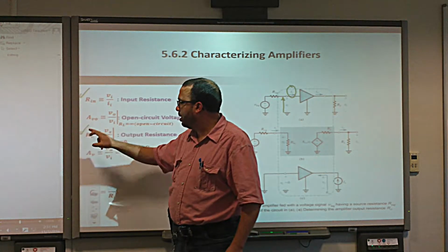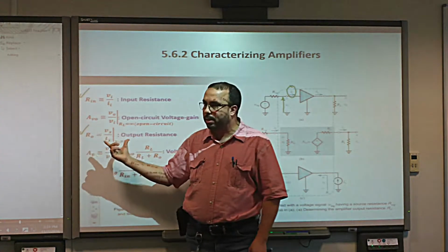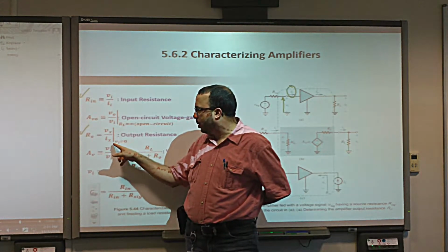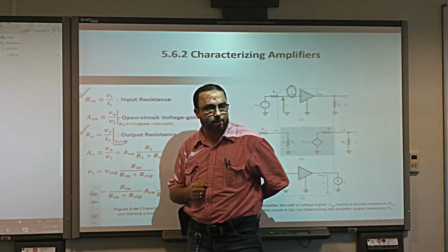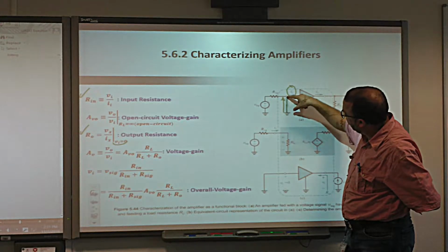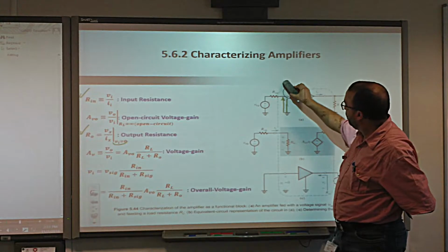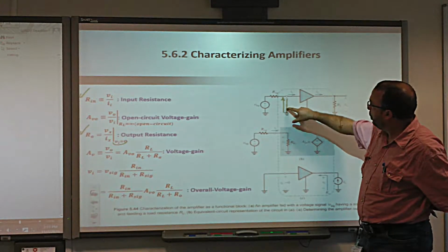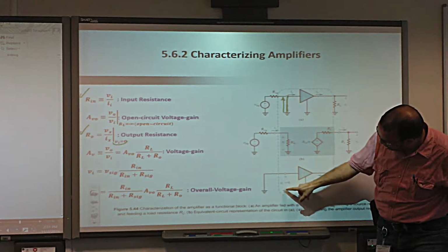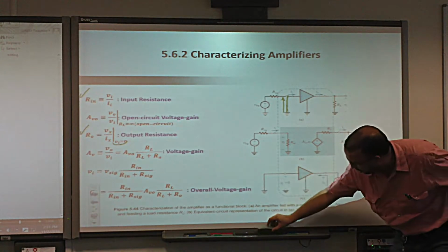The second resistance that is characteristic of an amplifier is called the output resistance. This one is a bit different, not too much. The condition for the output resistance is that we put the input voltage to the ground. I ground the input, so I make a connection with the ground now, so I don't have any input current, okay? So I ground, first of all, the input, so it's going to be like 0, okay? I cannot do this, this is just not to confuse you.